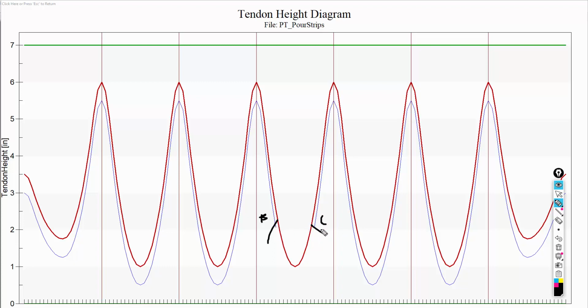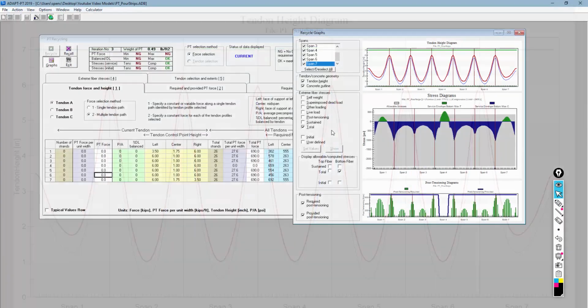And if we prepare a stress calculation, we know that if there's no counteractive equivalent loading from the post-tensioning, we're going to get significantly higher stress than if there were counteractive loads from the PT. We're not doing any load balancing essentially. So at that location, you can see we have high stress, and that's okay. This is not being designed as post-tension, so this exceeds the allowable.